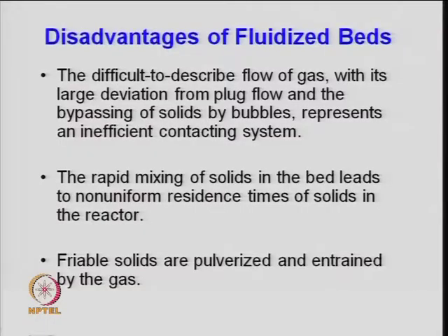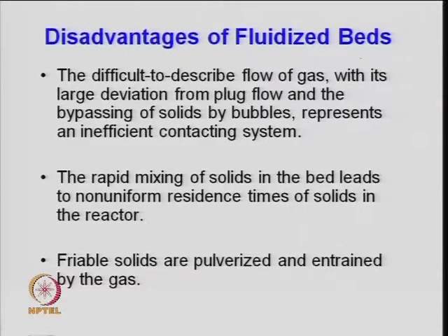When you try a high velocity, there may be bypassing of the solids by bubbles, right, there may be a kind of channeling. Some unwanted effects, because more and more voids will come, right, and the gas may channel through those voids. So, this is again a problem when you try to maintain plug flow condition in a fluidized bed reactor. And rapid mixing of solids in the bed leads to non-uniform residence time of solids in the reactor. As I said, there is a degree of back mixing, the solids are moving up and coming down, so there will always be a non-uniform residence time distribution.